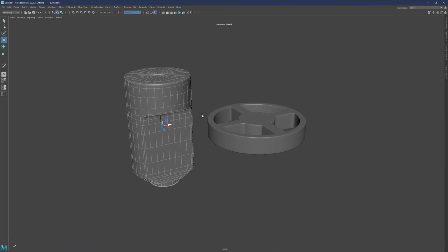So two examples. Cylinders, like I mentioned, they can always be tricky. It's just going to be dependent on really what you want to do. If you want to have a lot of details, you're going to need to balance that you do not start too dense, because that may also be hard to manipulate. A lot of edges is always going to be harder. So if you can start with, let's say, a smaller division level, something like maybe 20. I sometimes even start with 16 and then just subdivide it later if I need it for details.